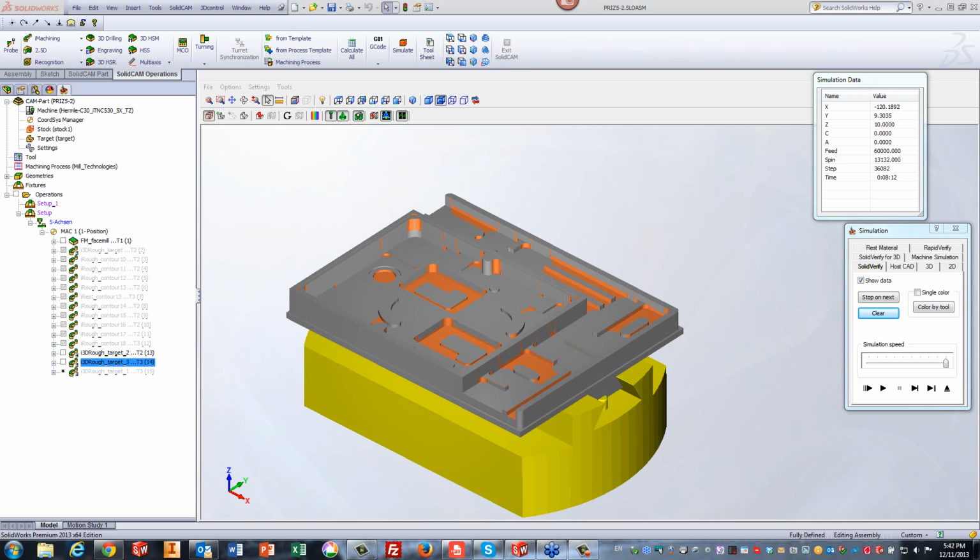If you ask me how to do a finish cut on a part like this, I would use the HSM using the prismatic part option, or a combination of linear and constant Z and horizontal floors. But as far as everything else goes, the iMachining goes over here. This is a really nice way to work, especially when you're doing prototype work. Okay, let me go into the questions now.